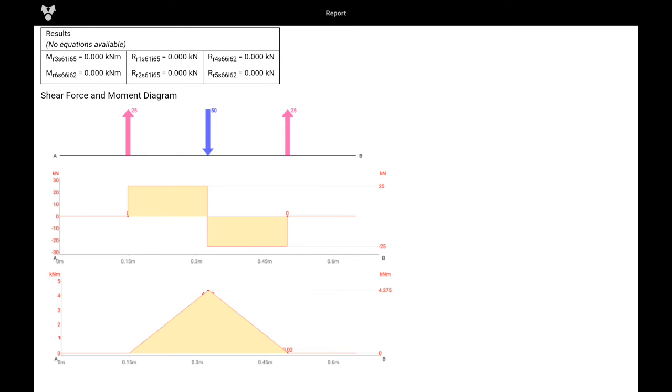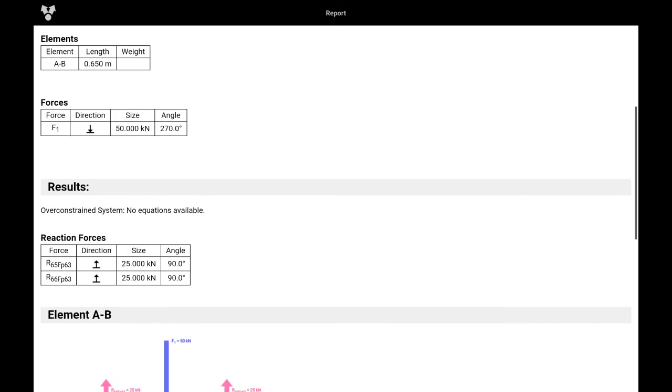And of course you know your loading, like maybe you're dealing with 0 to max loading or something of that sort. You can just jump right into finding your other information that you're going to need to determine a factor of safety or an endurance limit, things of that sort, material selection. So very helpful in that regard.